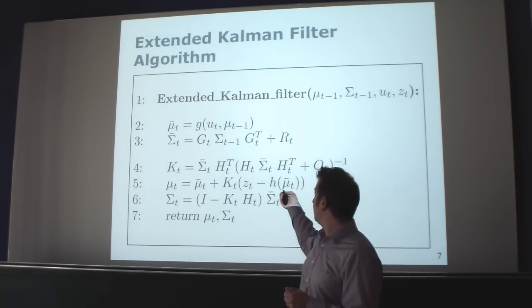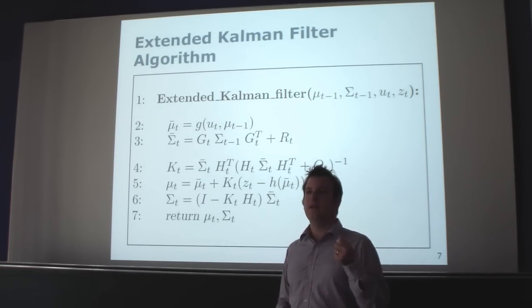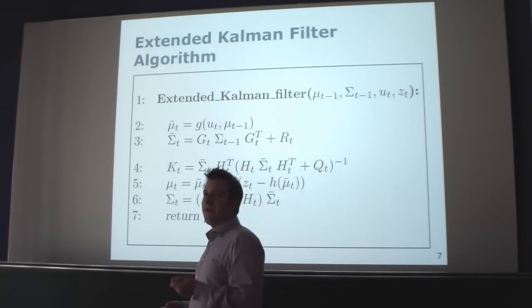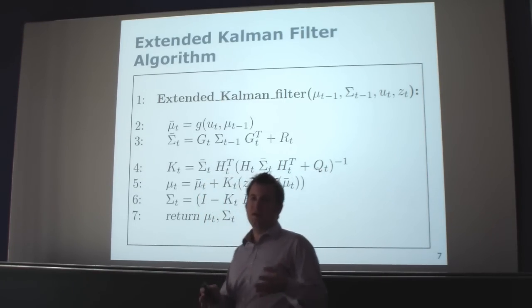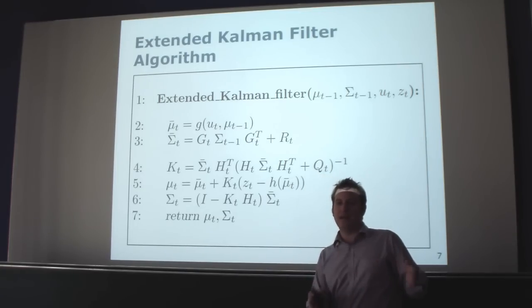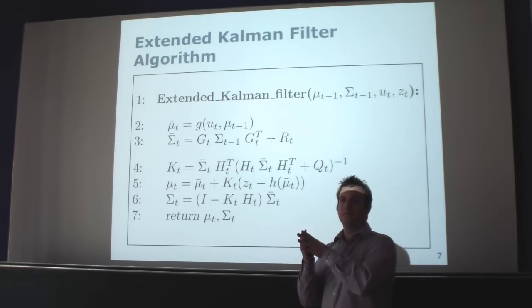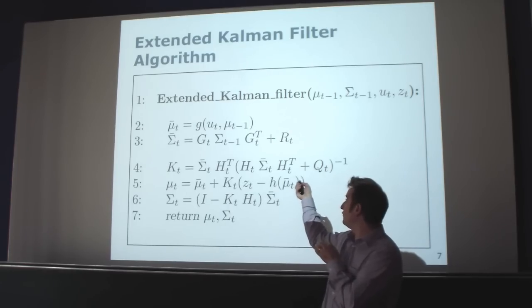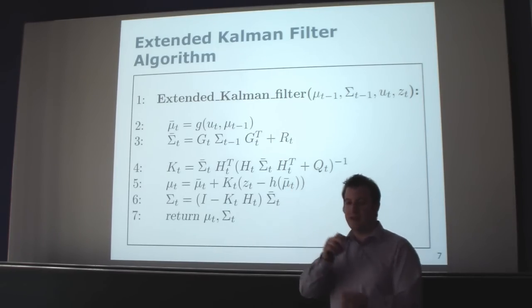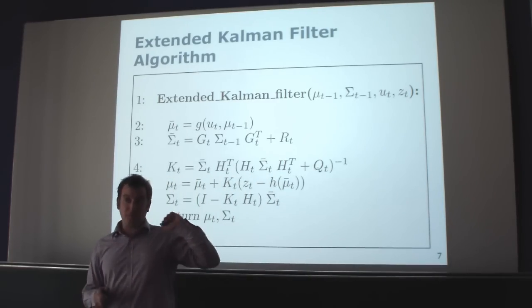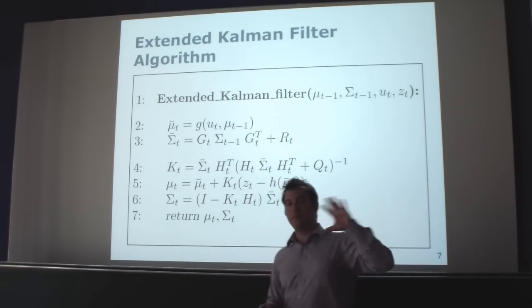Of course, this term here only affects the pose of the robot. So just by carrying out a motion command, I don't want to change the uncertainty about the landmark locations. This only affects the robot's pose. So you have to take care of how this R_t looks given the dimensions we put into our mean estimate. So that was the prediction step.